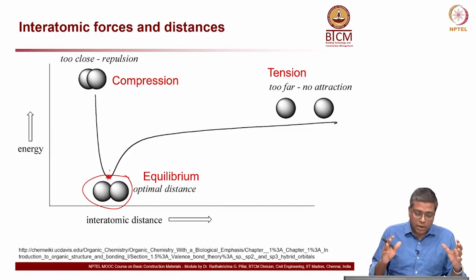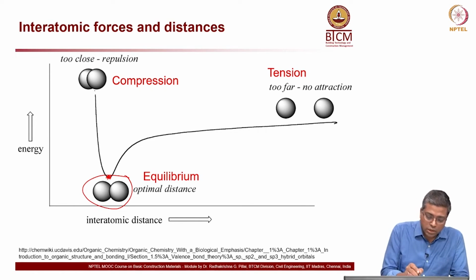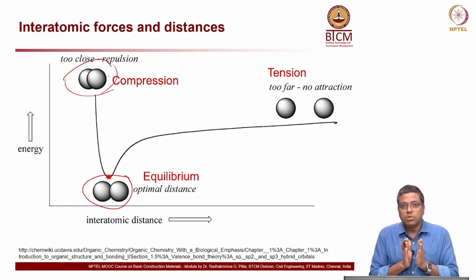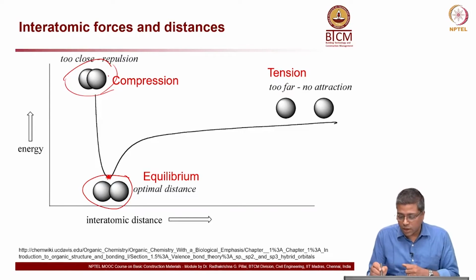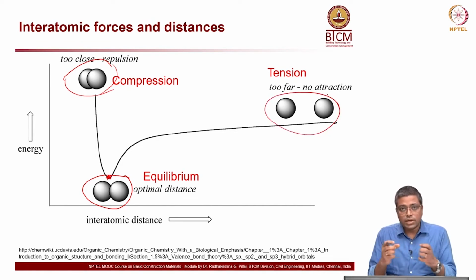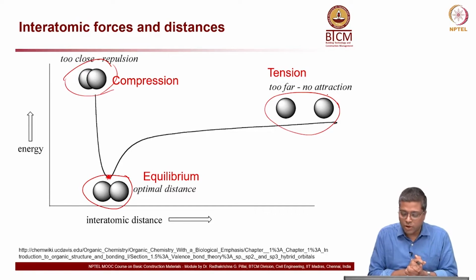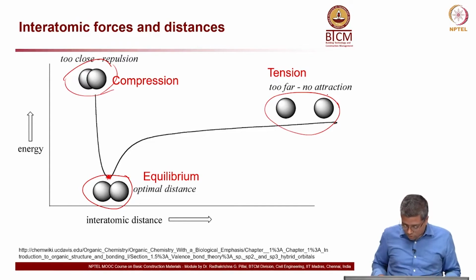Now, when you compress these 2 atoms together, you are getting this state here. The distance between the atoms is going to decrease, then definitely there are some repulsive forces created and then the energy level is high. And when you pull them apart, which is this case here, the interatomic distance keeps increasing, and as you pull there are some attractive forces generated, which keep the material together.